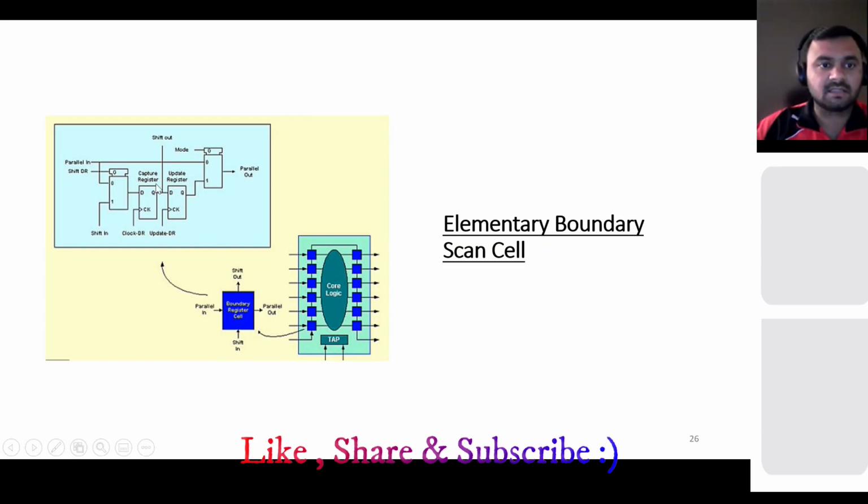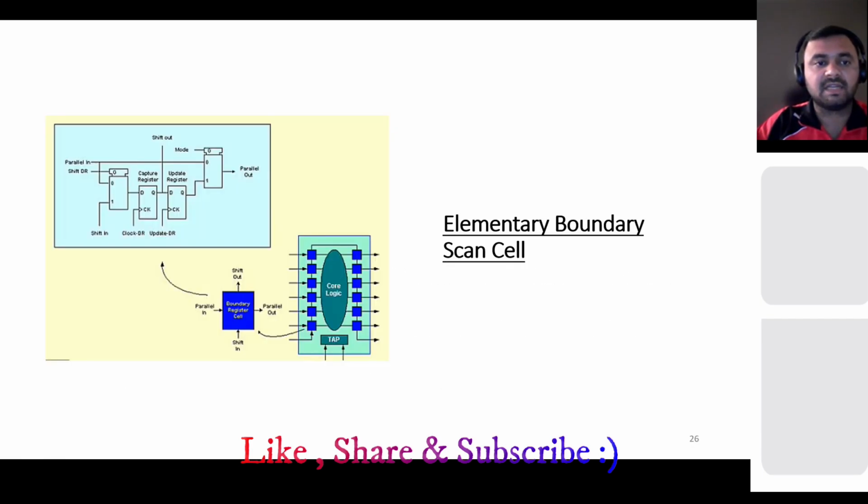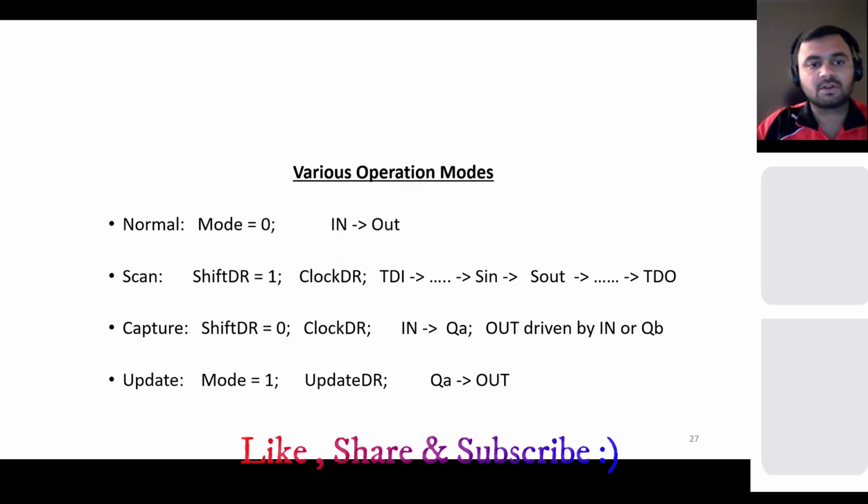You just use this clock DR signal, and you capture this shift DR shifting data here, and you put it to the shift out. And in the case of update, you put mode equals 1, and update DR mode equals 1, so that I will select this path and update DR, and it will latch your data to the output. This is just a fundamental basic operation of any boundary scan cell. So this is how we use it for normal scan, capture, and update.